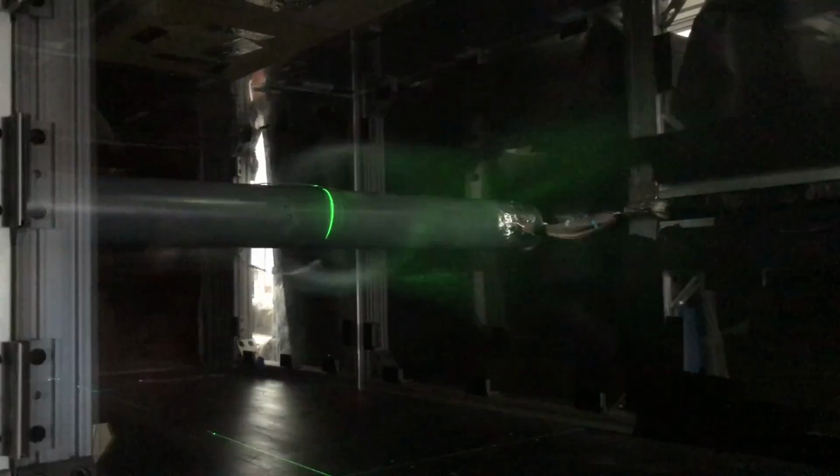It was required that the tape did not cover any pressure ports, thus causing some disruption of the flow and probably interfering with some of the pressure ports. There is also the concern that the surface may not be a perfect circle, which may alter the relationship between the potential flow equation and the data collected. With multiple groups testing and placing trip strips on the cylinder, it is likely that it may have been moved or slightly jostled at some point.